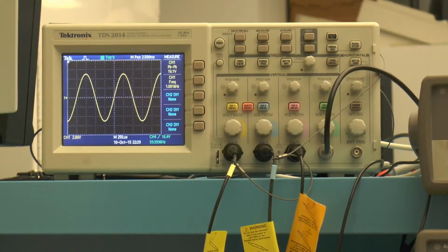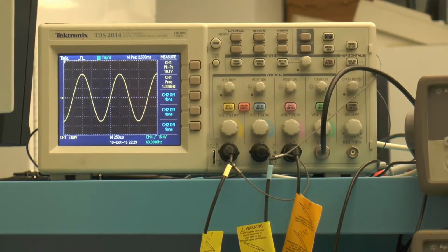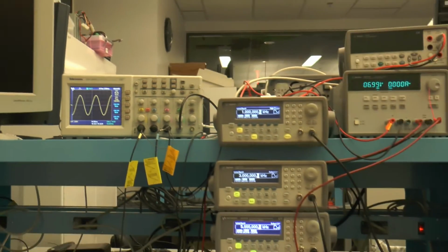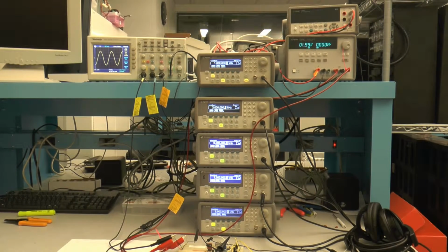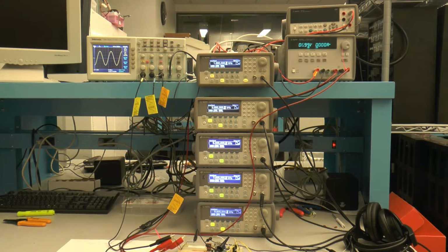Okay, here's our experimental setup. We're going to use our scope to look at the output of the summing amplifier. And there's our 5 function generators. One thing that's not shown is there's actually a 6th function generator. You'll notice that when we add together the sine and cosine, they both are in the same phase. And the only way to get all of these function generators to start at exactly the same place is to start them with an external trigger. So in the back of each function generator, there's a trigger input. I've got that connected to yet another function generator that's starting them all at the same time, about 60 times per second. So let's take a look at what we've got.